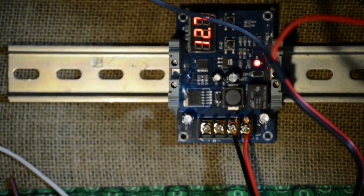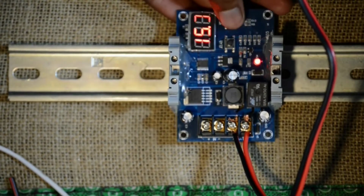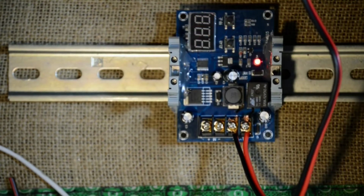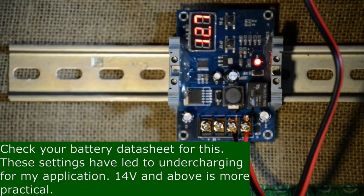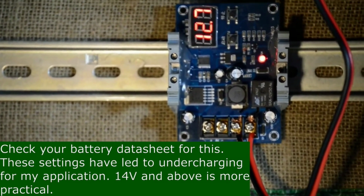And so what we're gonna do now is actually set this. So you long press the button on the right to set your upper limit. So for instance, I'm scrolling down and saying I want to stop charging at 13.5. It will start blinking. And then once it stops, that is our set point for where it needs to stop charging, at 13.5 volts when the battery gets to 13.5 volts.